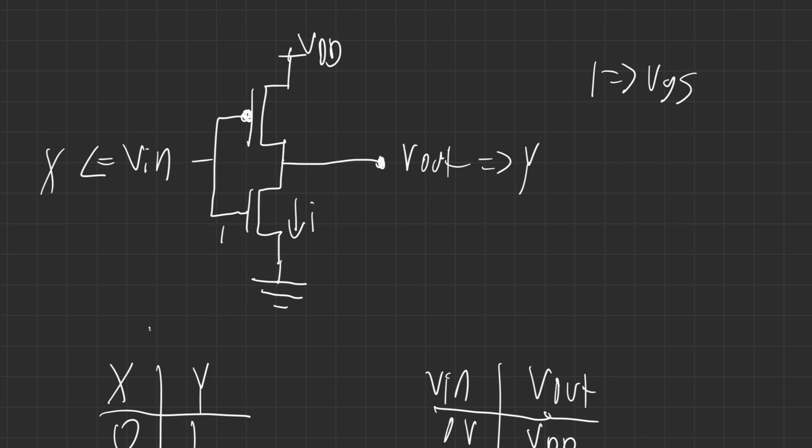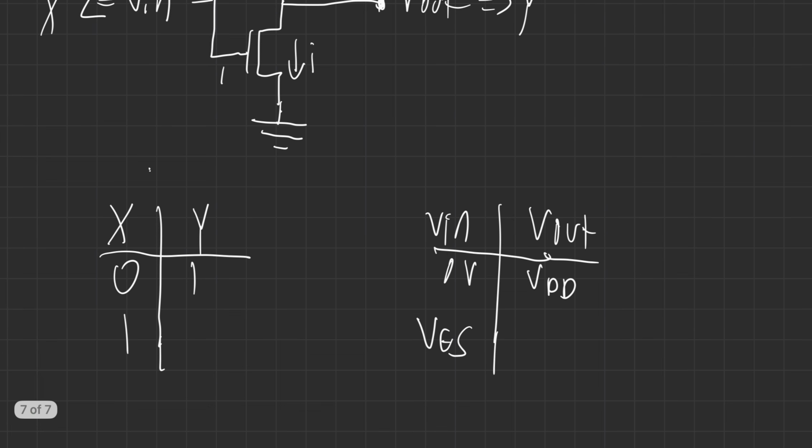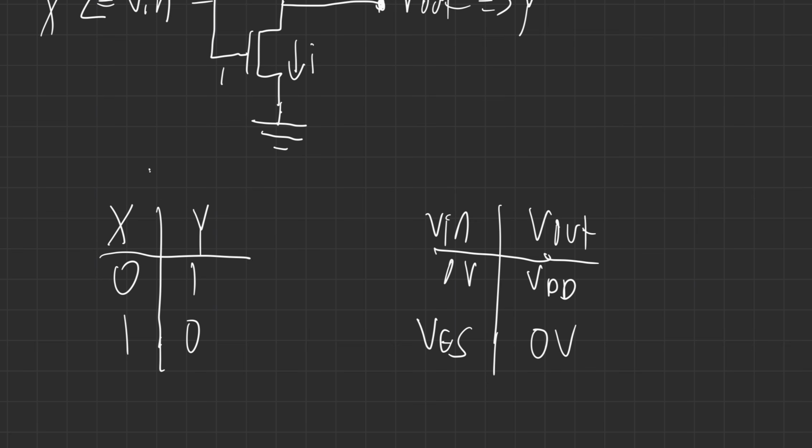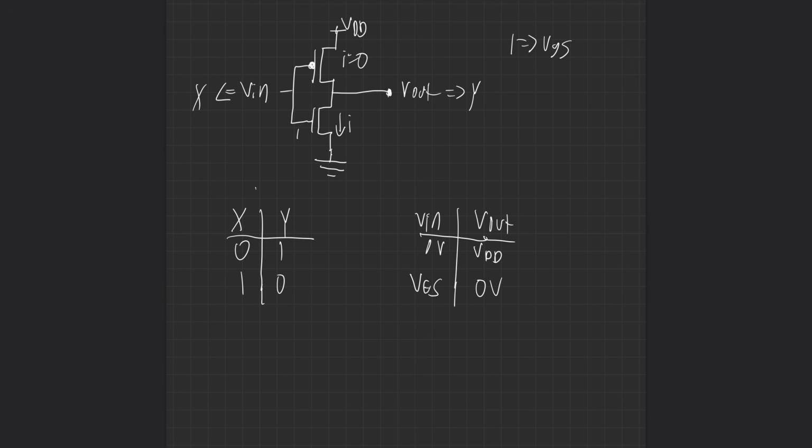And what's a 1 going to do over here? Well, it's actually going to block it. So this is going to be blocked here. So these two will be connected here from ground to V out, right? So what does that mean? 0 volts. This is a logical 0. So you have, through this, built your first inverter circuit and your first CMOS.